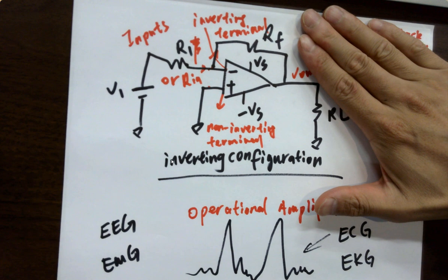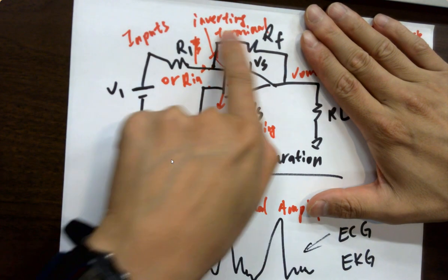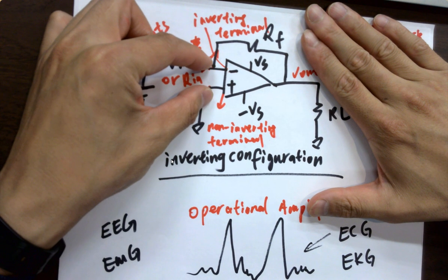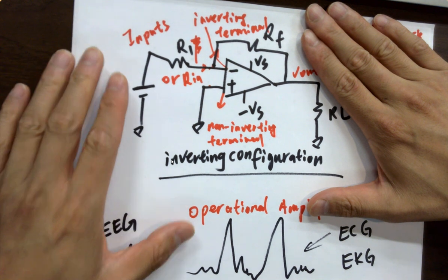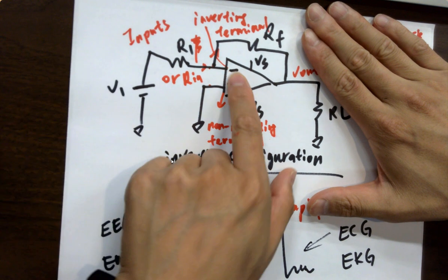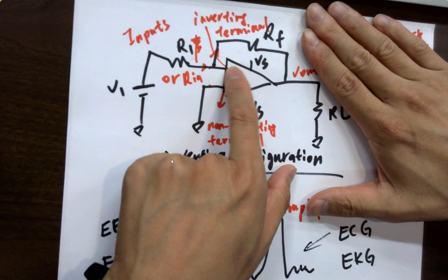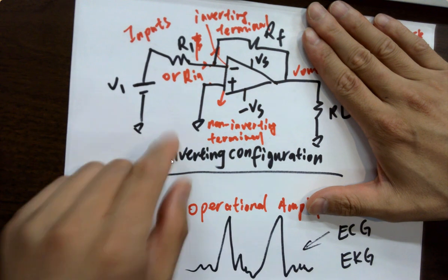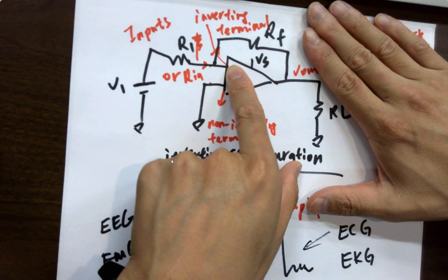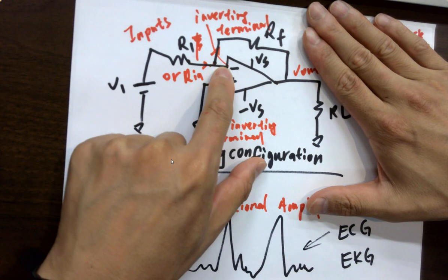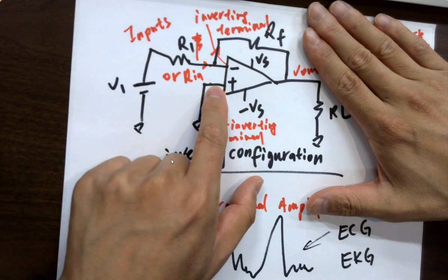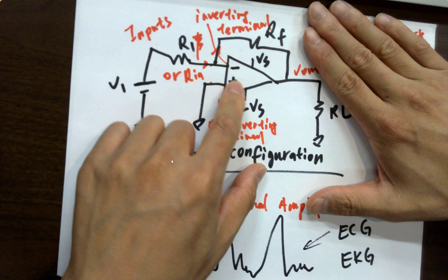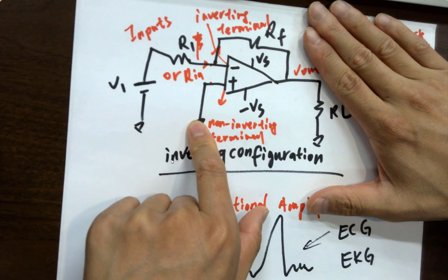Now let me ask you these questions. Is there a feedback? Yes. Are they equal? Yeah? First on the list. Okay? Input resistance is infinity. It's going to push all the current out. Or no, I shouldn't say that. It's going to disconnect, similar to a disconnected circuit. So eventually no current over here in this little wire. Is there current flowing to the ground? No, no current going in, no current going out. So no current in this wire.